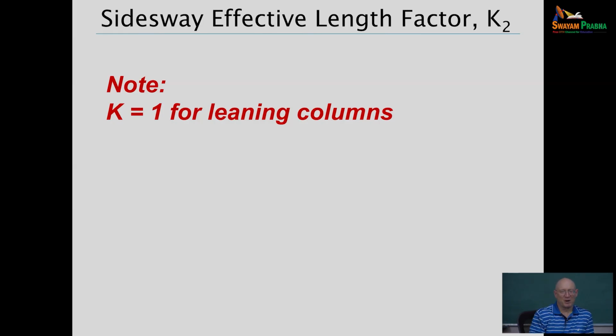Then comes the thing that's really confusing with buckling-based solutions with side sway. You say, but I've got a very light, very flexible spring connection. That connection represented by a spring to top and bottom to a column over there on the right. Now you get into something that in the literature is referred to as the effective length factor paradox, where it's not so appropriate to use this really large K factor for something like that because it's not really helping the story.